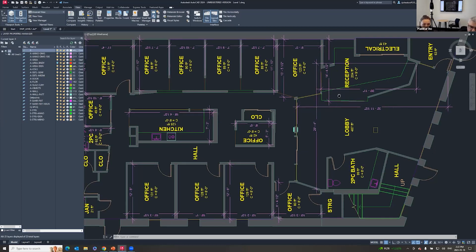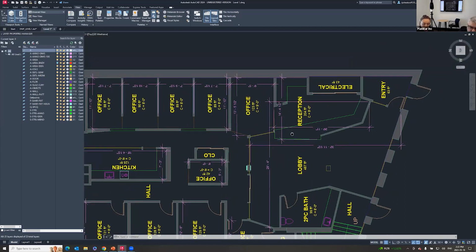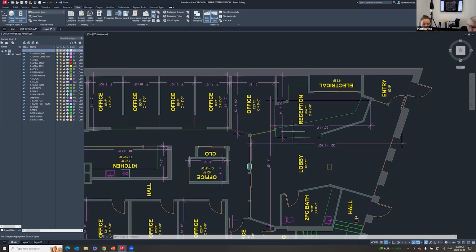Again, reiterating some of the other things we've talked about, standardized door sizes. When the LiDAR measured doorways in the past, and the draftspeople had to interpret the width of that door depending on the LiDAR data, with some subjectivity in between, we just drew it and said, hey, there's a door there. Now we're using drafting templates that say, hey, that's got to be a 30 or 32-inch door, whatever the standard sizes are. And as they drop that in, we get all the parameters about it.